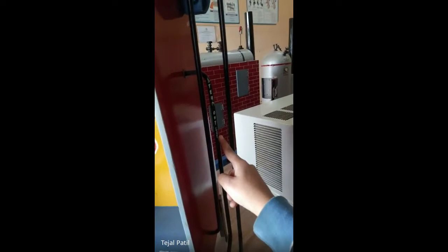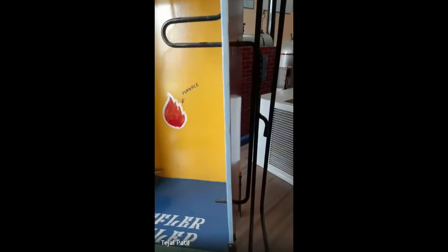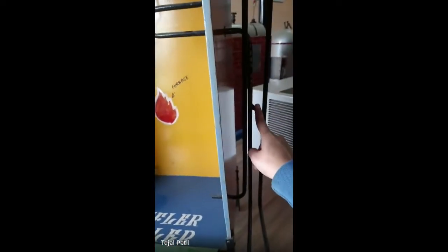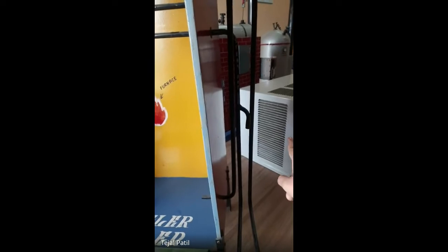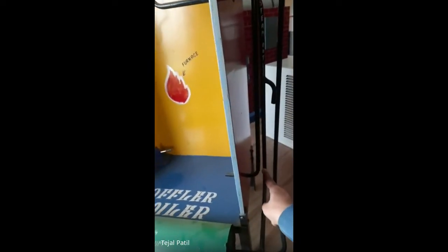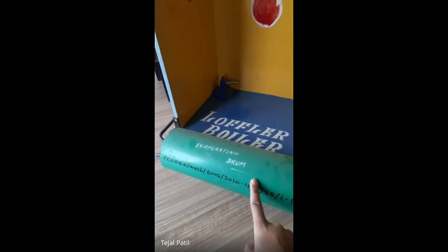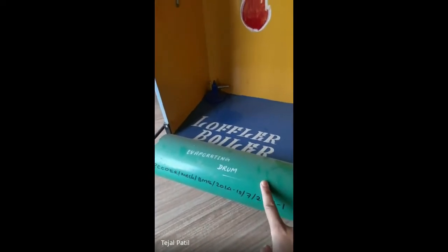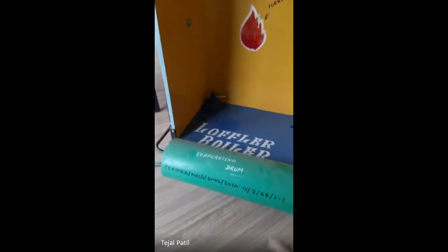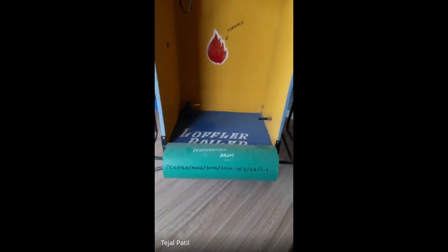Then after that, you can see here is the outlet from the superheater, and this is basically the outlet of the steam. Wherever the steam is required, from here that steam will be taken. For this type of boiler, the Loeffler boiler, 1/3 of the steam will be taken to the place where it is required, and 2/3 of the steam will be sent back to the evaporator, so that the water inside the drum will be converted into steam. So this is basically for the Loeffler boiler, but it is not the same every time.